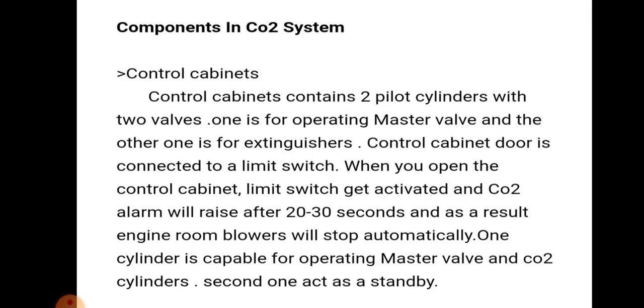The control cabinet is connected to a limit switch. When you open the control cabinet, the limit switch gets activated and the CO2 alarm will rise after 20 to 30 seconds, and as a result the engine room blower will stop automatically. One cylinder is capable of operating the master valve and CO2 cylinder. The second one acts as standby.